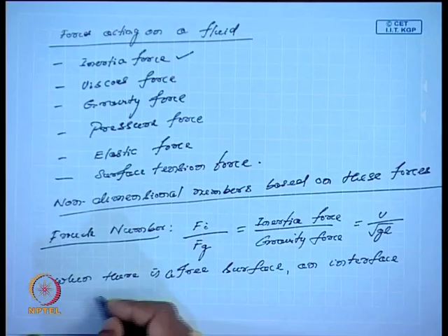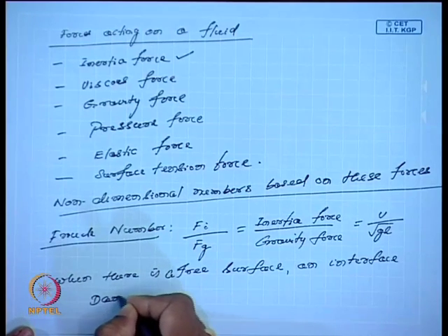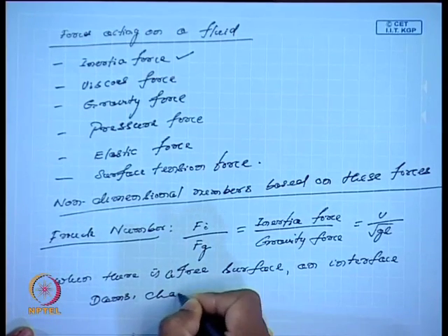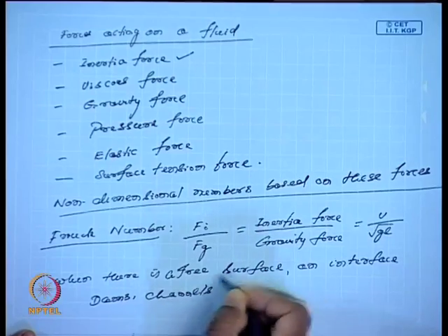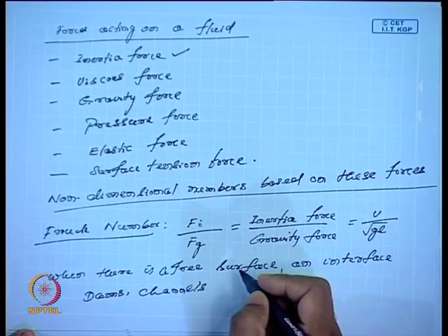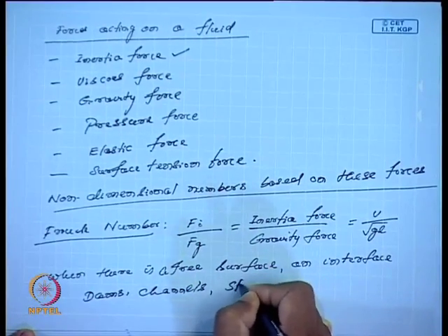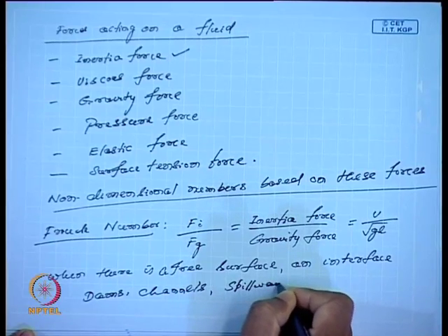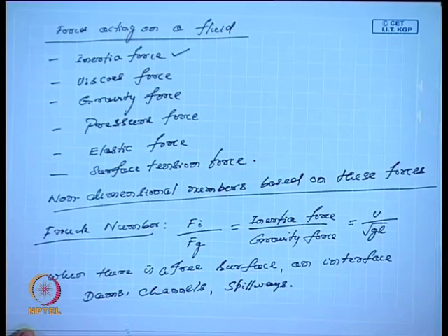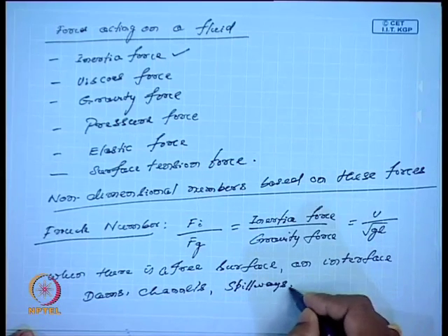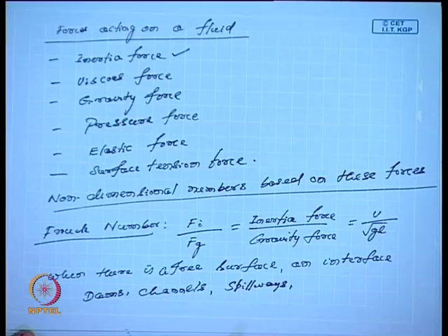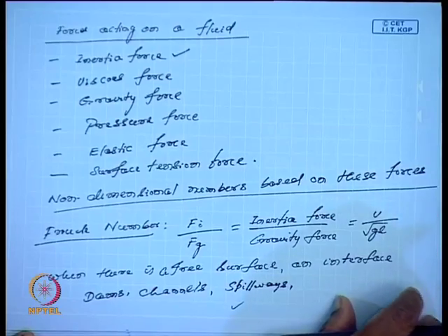And more important are the problems associated with dams, channels, and spillways. This Froude number plays a very significant role, because here the surface elevation plays a significant role, and the gravitational force plays a more significant role than even the viscous force. This is the Froude number's importance.